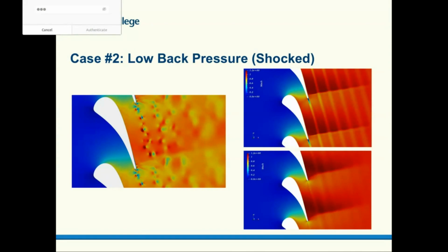where the pressure on the suction side, so the two sides of the airfoil flow meets and sort of forms these high energy structures, which are really complicated to get to sort of work with the flow solver in 3D. We're having a lot of difficulty because of the high energy that is generated by the high suction. And then you have sort of the unsteadiness of the shock.